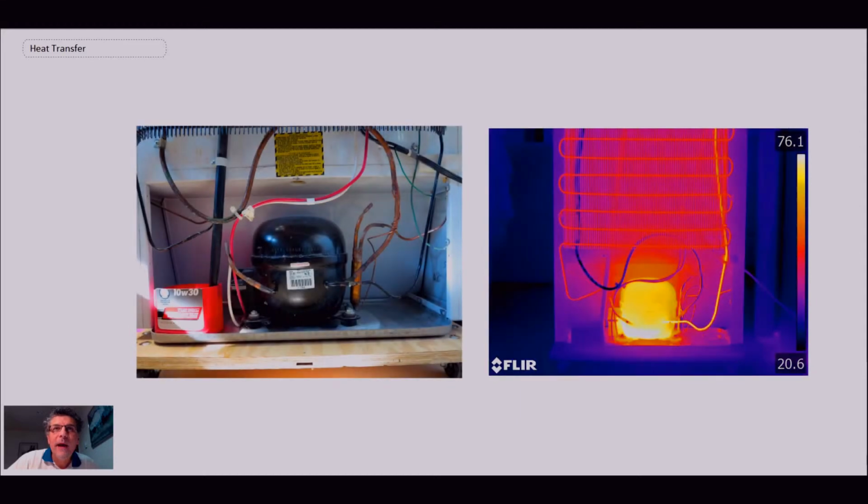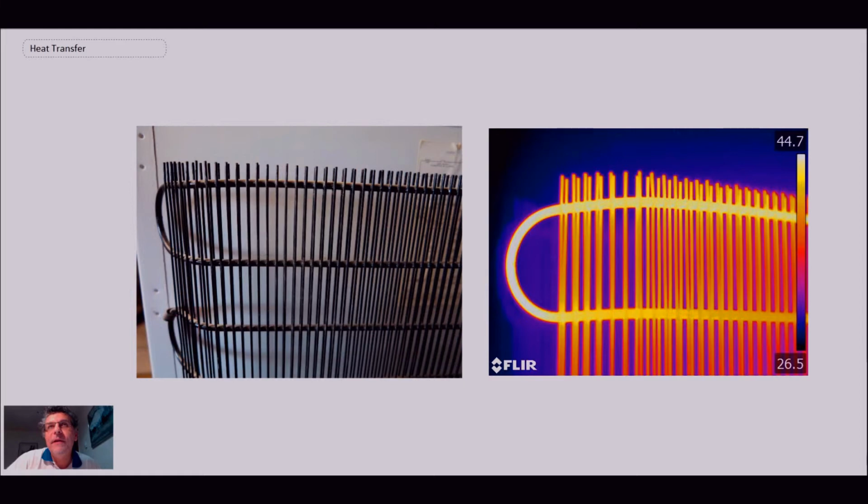Now, another application that we have for condensing is in refrigeration. And so here is a picture of a refrigerator. It's an older fashioned refrigerator where we have coils on the back. But what's happening on the inside of those coils is we have condensation occurring. So the refrigerant becomes a superheated vapor after the compression process, and then we reject heat and it's going through a condensing process.